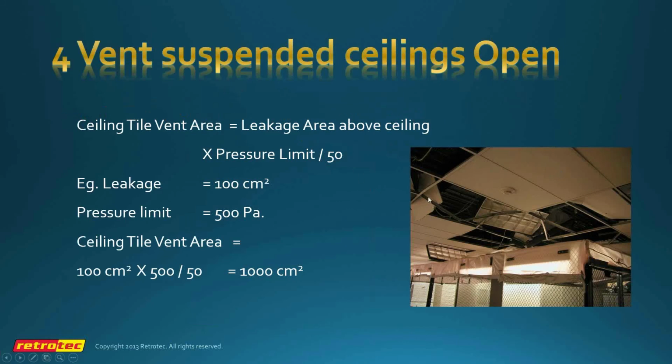And the next one is to ensure that the suspended ceiling is properly vented, so that when the discharge occurs and the agent is trying to find its way back to the holes above the suspended ceiling, it doesn't take the ceiling with it. So we have a very simple formula for doing that. That's something that we certainly need to be looking at whenever we're inspecting an enclosure.